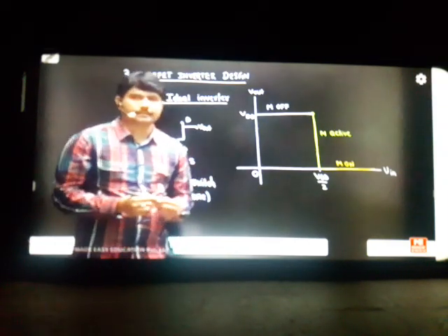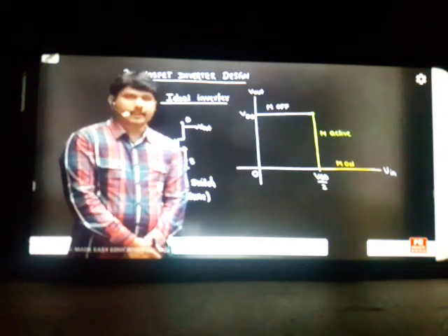This is the ideal switching characteristic in digital designs. So I think my MOSFET is not an ideal MOSFET. It's a practical one. Maybe this type of graph may not come, but to get this type of graph, the analysis is to modify the circuits and apply the ideas such that finally this graph comes. If you get this type of graph, you can stop the analysis. You got a good inverter, we can say. Until this type of graph comes, it will not work as a good inverter.